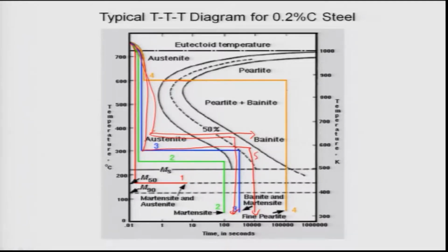But normally it is cooled rapidly so that the pearlite which formed at high temperature does not get changed when it is investigated further. So that means this is temperature versus time, and each of these curves is a cooling curve. Simply by changing the cooling curves, one can change all kinds of microstructure. That is what is important for you to understand.